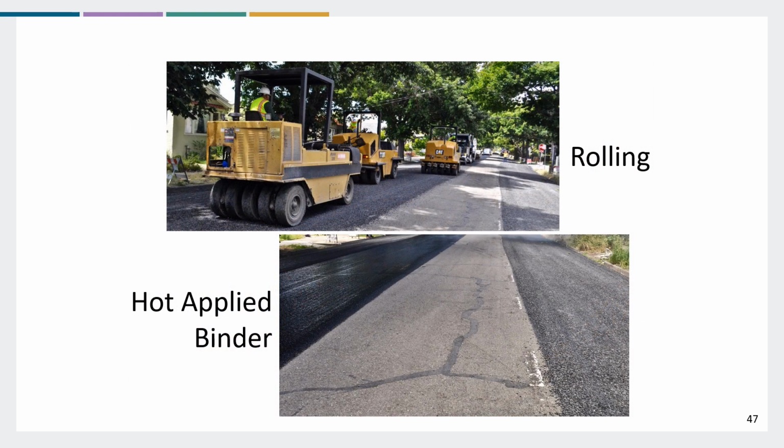Directly behind the chipper are the rollers. You want the rollers evenly spread out and really embedding the aggregate into the oil or the mat. This is a picture of the city of Berkeley applying an asphalt rubber chip seal with a hot applied binder, and the aggregate is pre-coated. And as you can see, the city did all their prep work prior to the preservation treatment going down.